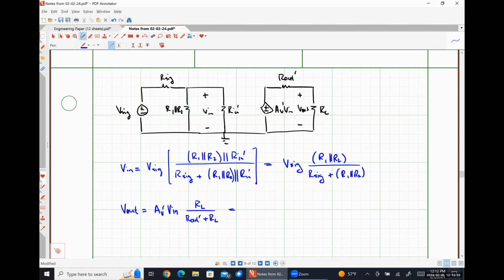So that's going to look like, I'm putting the gm in there just in case I need it, negative gm RD times 1 over gm divided by RS plus 1 over gm.